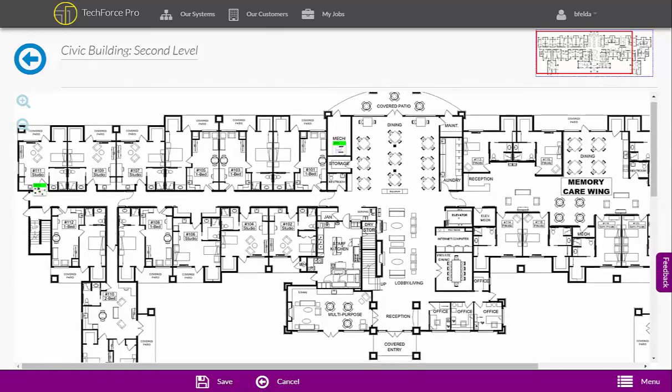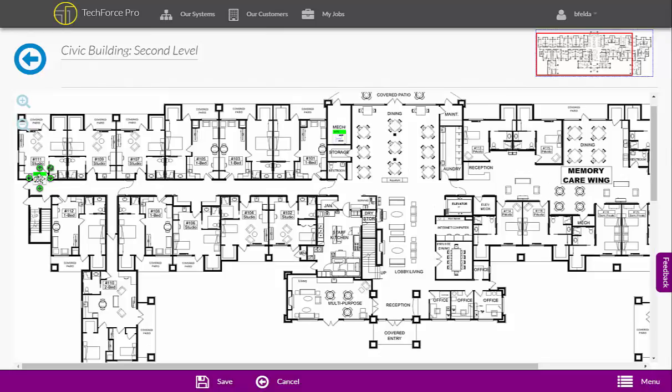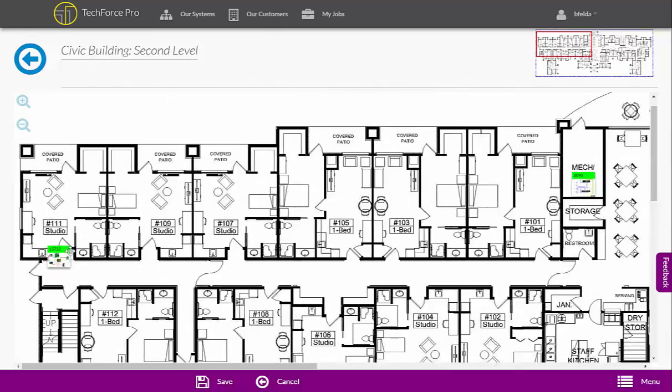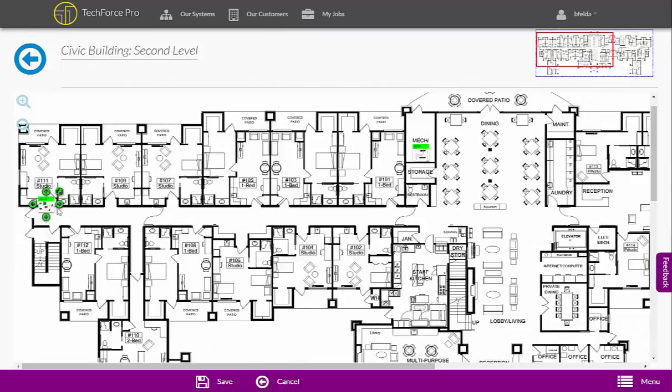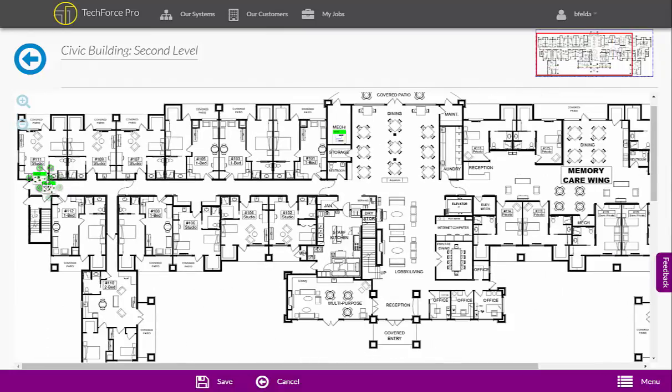So let's say, for example, that this system is a good starting system. It's got some parts that I want to use at all the doors. So we'll make a copy. I'll zoom in here so you can see when I hover over it, there's this copy icon. So by clicking on that copy icon, it makes a duplicate of it, and I can drag it to another location. Click it, drag it to another location. Now we have 3 copies of that system.